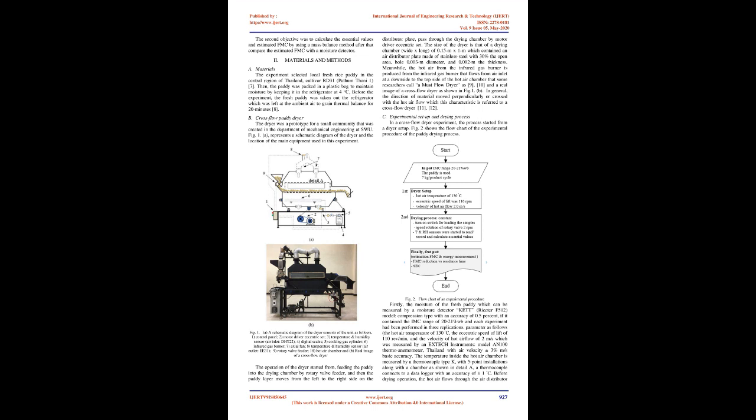Typically, the dryer is a tool to remove water contained in the paddy grain by using heated airflow passed through the paddy layer, which causes heat and mass transfer between paddy grain and hot air. The paddy should be dried to 15% WB moisture content to trade at the rice mills without reducing the trade price due to moisture content, or the appropriate level of 14-15% WB, then it will be ready for exports, preservation, and storage.